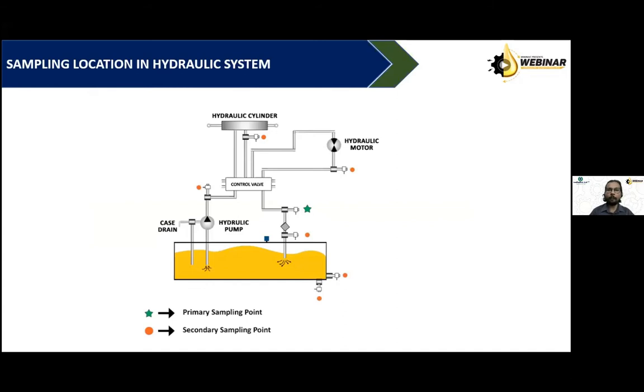Now coming to maintenance side of hydraulic circuit. Hydraulic circuit can run for years trouble free with only one solution, if we can control the contamination in the hydraulic fluid. Hydraulic circuits are mostly closed loop circuits. So there is very little chance that external contamination or external air will come in contact with the oil during operation. But what about the tank?